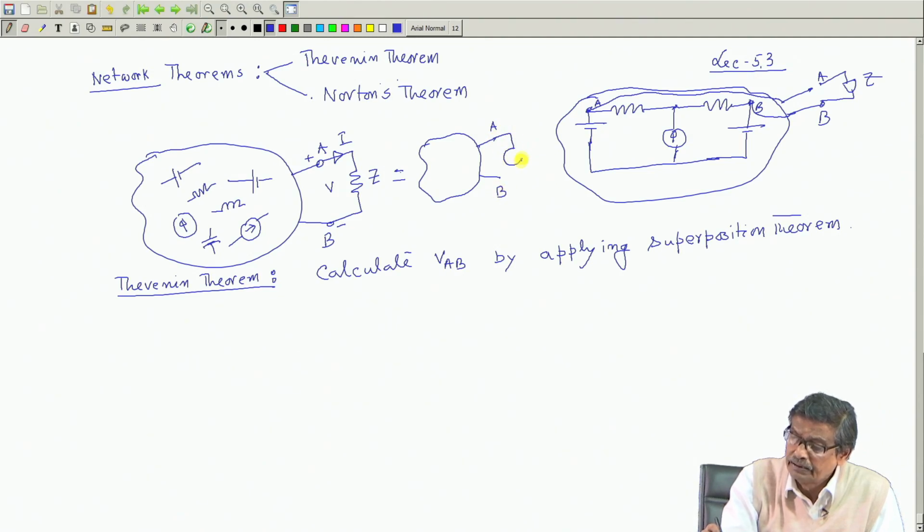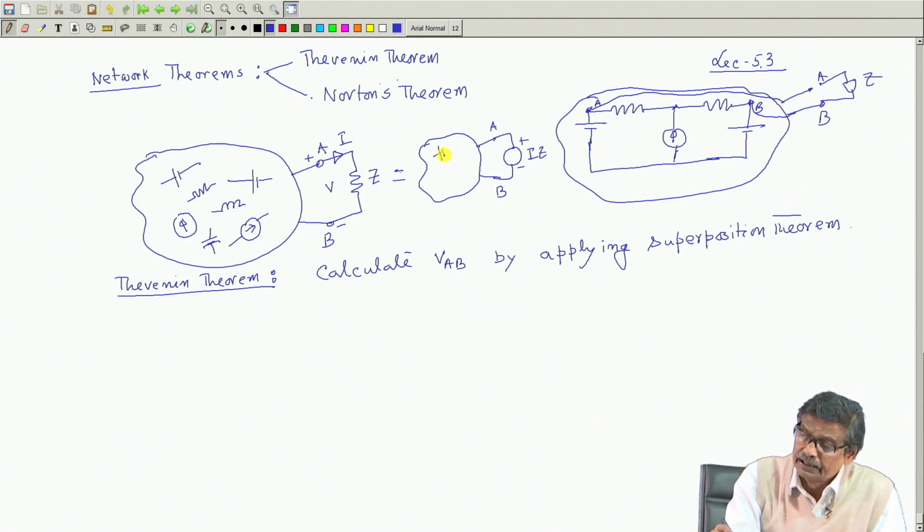Here this one, by substitution theorem I can say here is a voltage source I z of this. These two networks will be no different. So, what I am planning to do is this, that there are several sources inside the network, several elements, current sources, what not, and across AB this Z is connected, current is I. Therefore, this branch can be replaced by a voltage source plus minus I z, and it is not going to alter any branch currents of this network here.